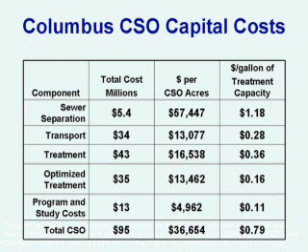Subsequent to implementing the program in Columbus, there was a comprehensive multi-year watershed monitoring and modeling study where over 6,000 sampling points were obtained dealing with bacteria around the TMDL boundary for the CSOs, to show that, in fact, they were in compliance with water quality standards. The TMDL evaluation and implementation plan was also prepared, using the state's no reasonable potential analysis to support the no CSO effluent limit. As part of their permitting cycle, there's also a one-time priority pollutant scan. Initially, it was done for all 16 overflow points, and in subsequent permit cycles, it was for the 2 treatment plant discharges.